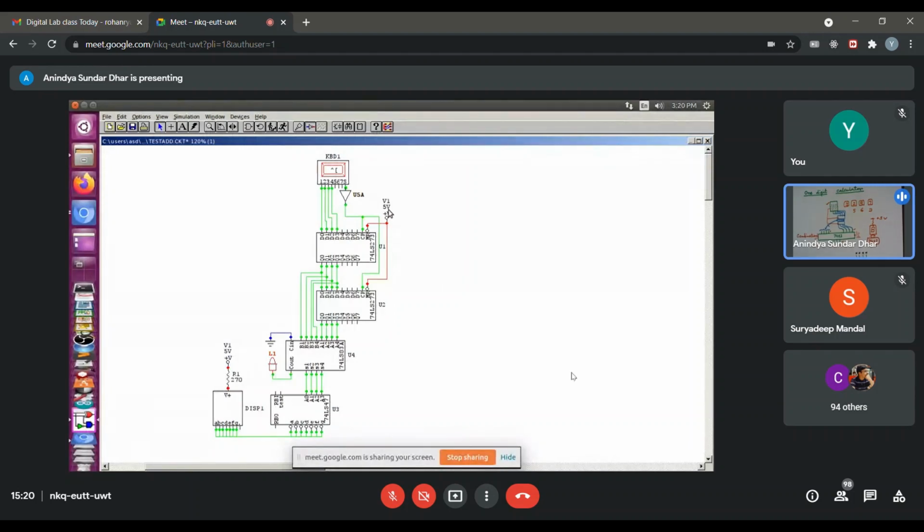In reality, you may say that if I keep them open in a TTL series IC, that also will be considered high. So is it a good idea to keep an input line open, or should I explicitly tie it to a high value? Any suggestion? If it is open, external noise could disturb and cause errors.